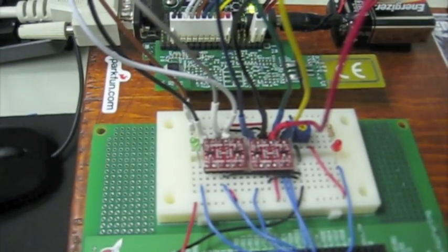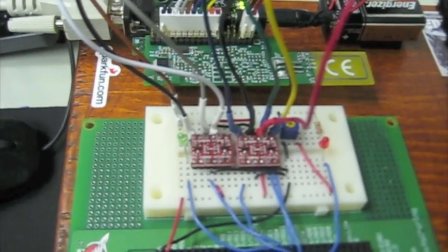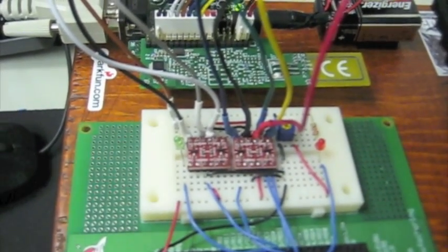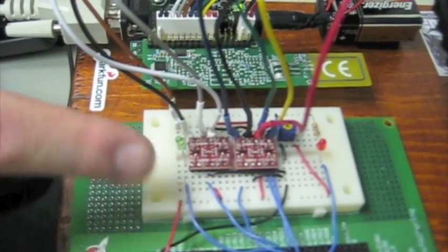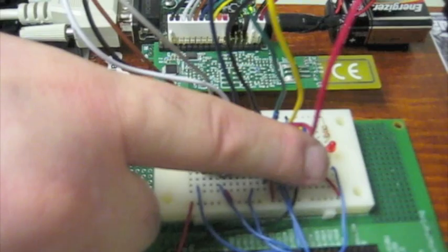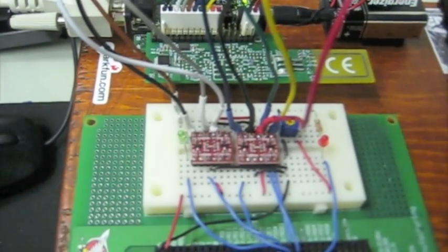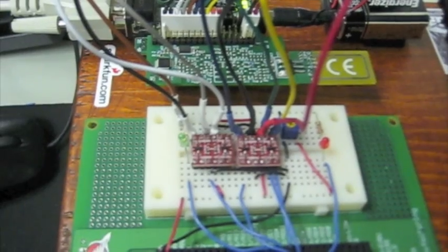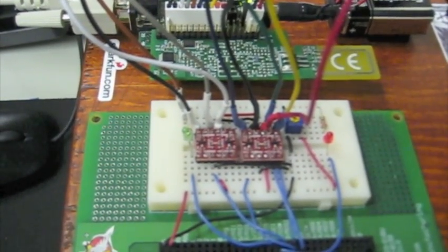Data is now being received by the receiver, and we have written a program that will monitor the SPI flag and blink a green LED every time it receives bytes of data, and will blink a red LED every time it receives a full 13 bytes of data. We have built in a timeout so that if it does not receive the full 13 bytes, it trashes the data and goes back to receive another full 13 bytes.